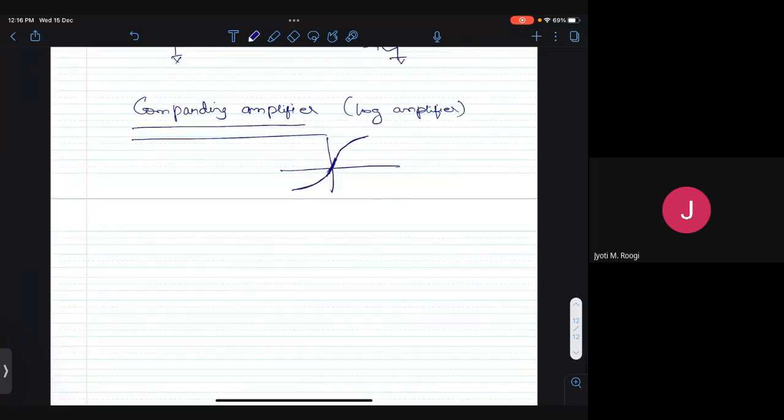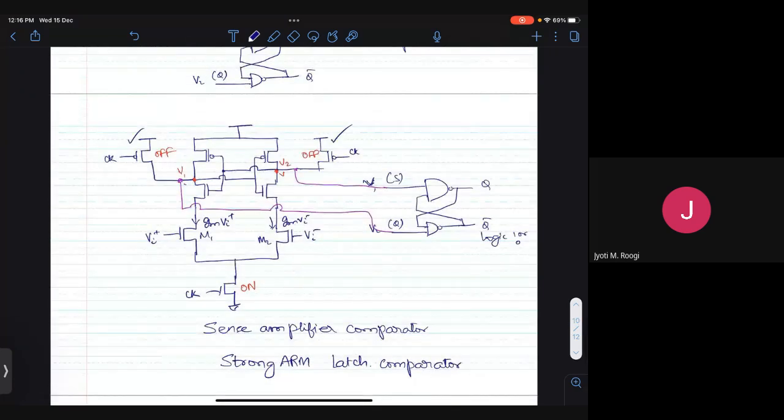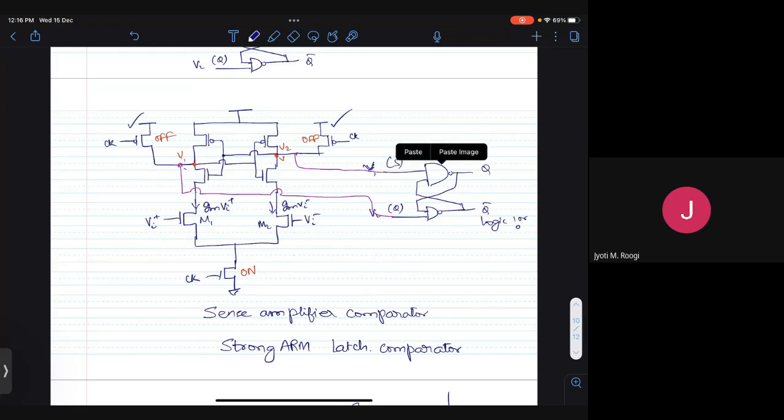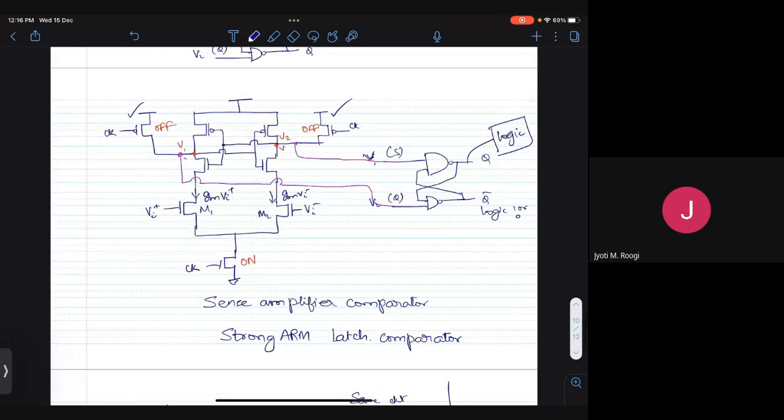Thank you, sir. Okay, so coming back to our discussion on these comparators, we'll have about half an hour left, right? We'll look at one of the problems with this comparator. Generally, when you design a comparator like this, a latch will definitely be required, which means that for the purpose of comparison, you need to generate Q and Q bar. But often you will not need to use both Q and Q bar, which means that in the subsequent stage, you may take this Q and connect it to some subsequent digital logic, and you may not use Q bar at all.